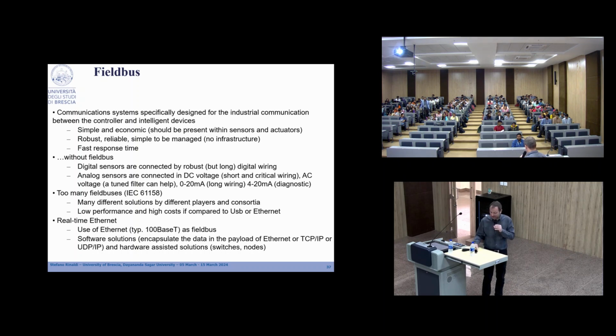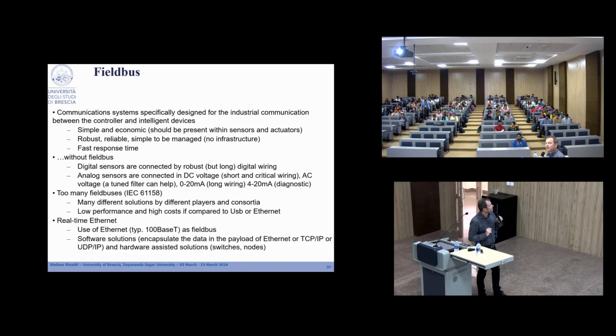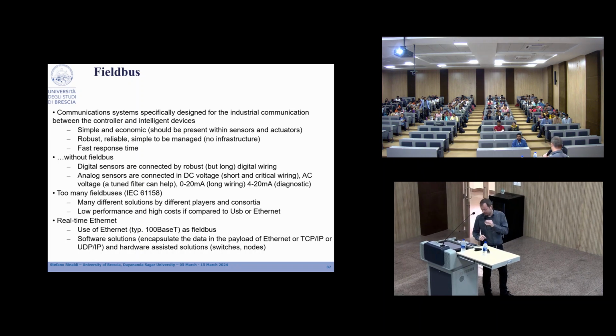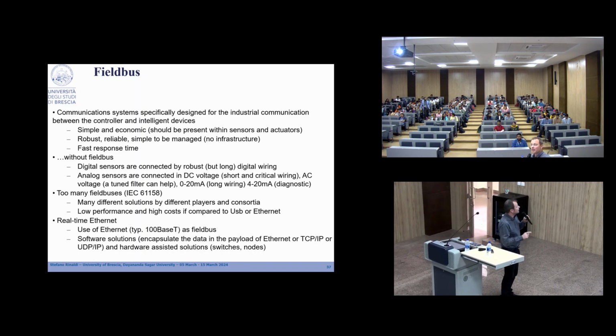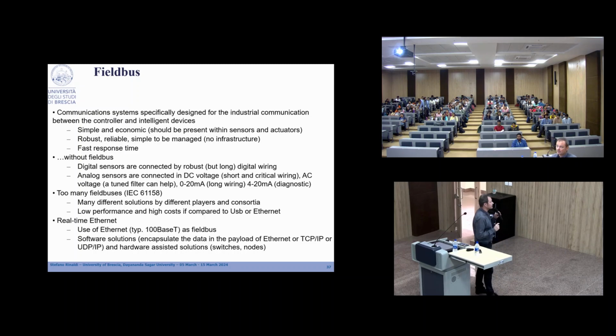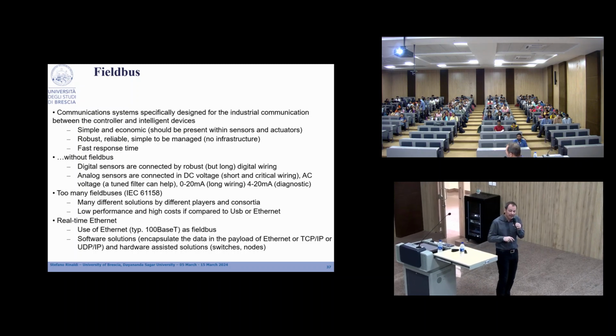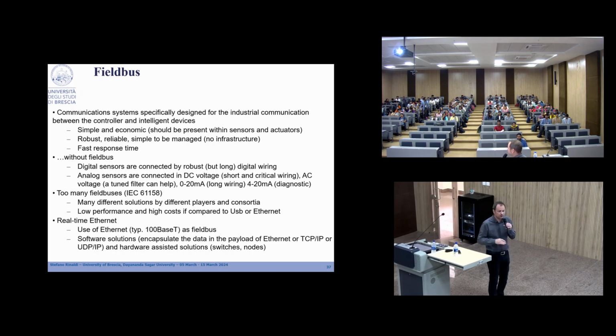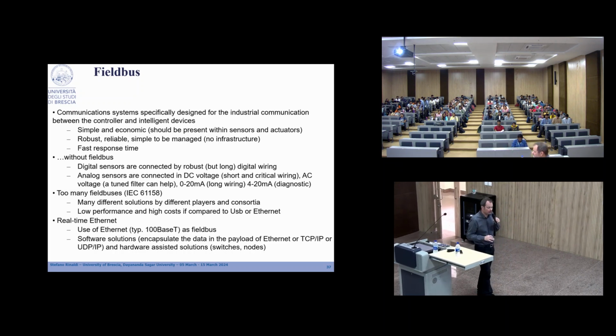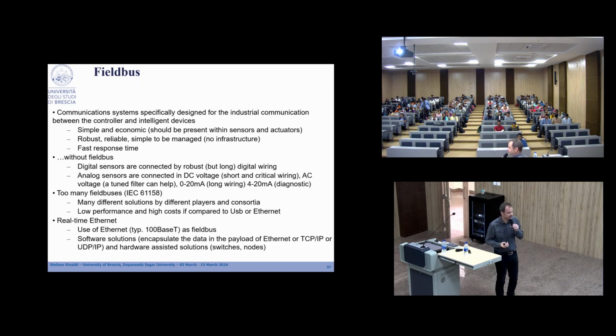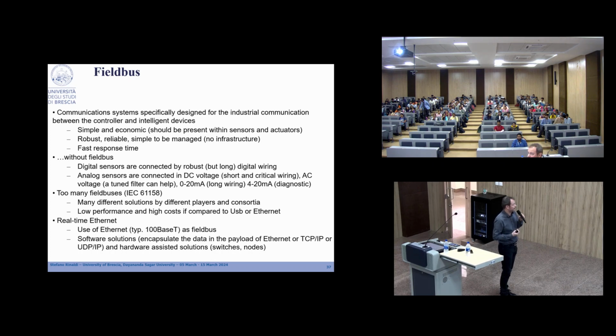I will go into detail on the field bus, which is probably the last slide for today. The field bus, as I mentioned before, is a specific communication network used just and only for industrial plants. They are dedicated systems with specific characteristics.